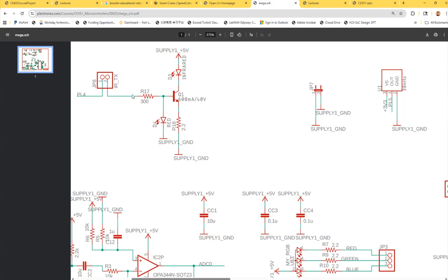All right, so you can use a different board to check it. You can get a functioning one. It's like a positive control. You know it works. So you bring it into your design so you can reduce the number of variables on the board. So you can keep debugging in the same way, right? Reducing the variables and narrowing it down to maybe just one single problem. So you can start working on that after that, okay?